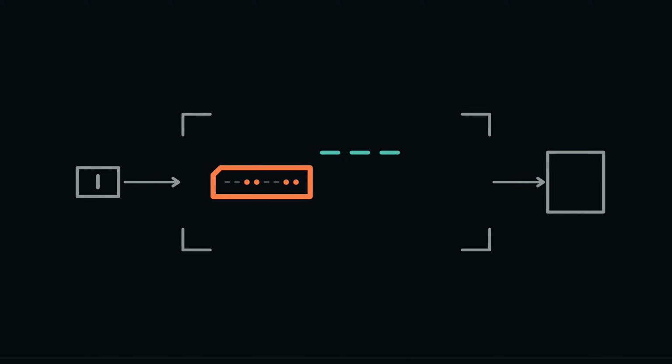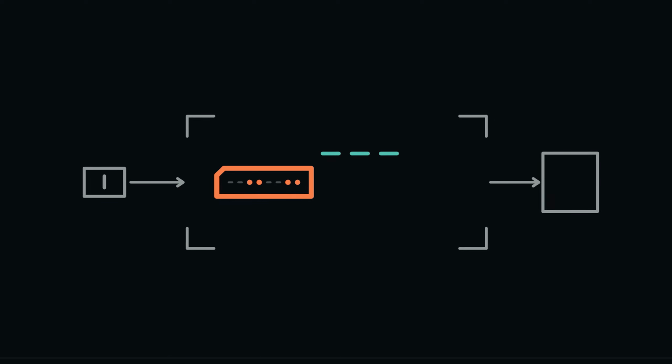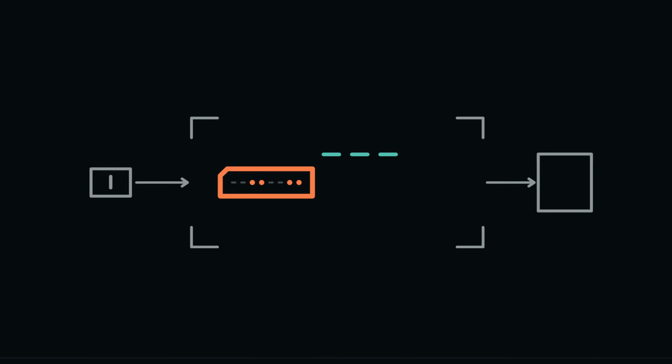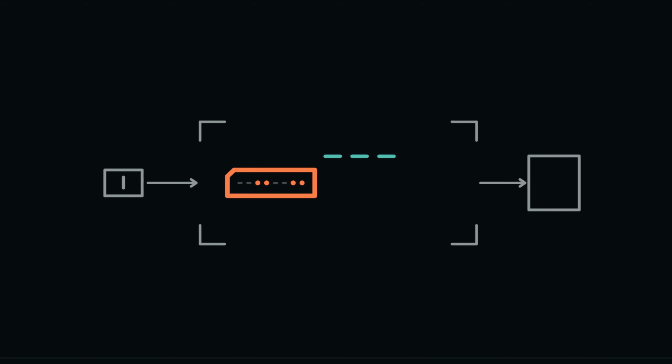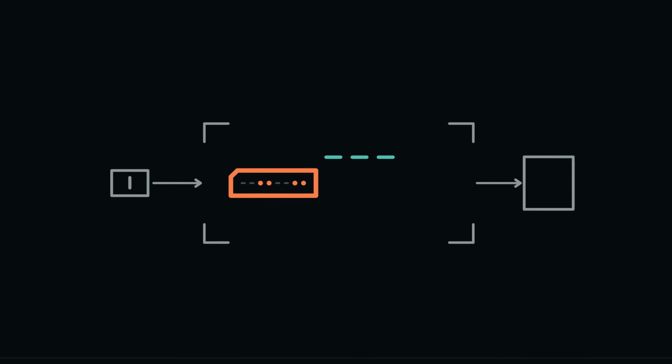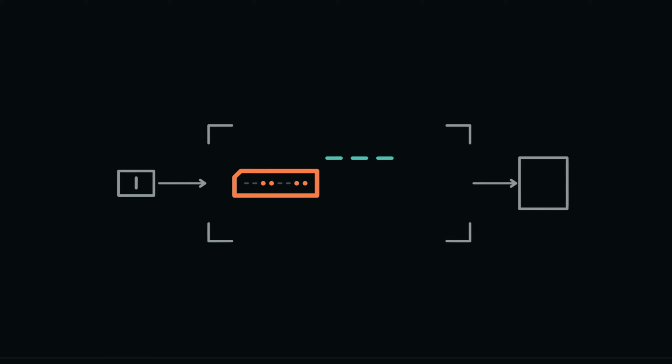The register we built remembers 8 bits at once, but 8 remembered choices are not automatically a number. Their order must matter according to an agreed rule. Keep the register in place while a weight appears beside each bit position. This is the same idea as place value in decimal notation. The digit 2 in 20 means something different from the digit 2 in 200 because its position carries a different weight. The mapping is useful. The limit is that our positions have only 2 possible digits, 0 and 1, rather than 10.